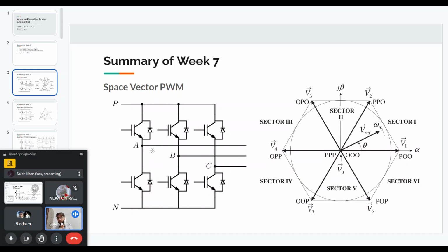That is where the term space vector comes from. When we provide three-phase balanced currents to these windings, the currents have a phase shift in time. So there are two things happening here: a positioning of the windings in space, and a phase shift of the currents in time. That means first the phase A current will reach its peak, then after 120 degrees, phase B will reach its peak, then after another 120 degrees, phase C will reach its peak. So this is 120 degrees in time.